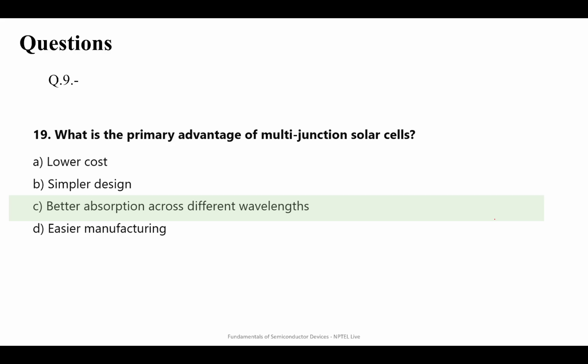Now if I put another semiconductor along with silicon that has a band gap of 2 eV, then between 1.1 and 2 eV silicon is absorbing, and above 2 eV both absorb, but the silicon is outputting 1.1 eV electrons. This material is outputting 2 eV electrons.